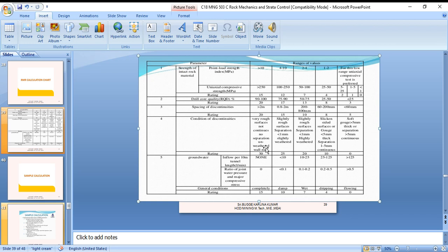Depth of the excavation, width of the excavation, and angle of fractures are also taken. Protodyakonov's coefficient is also one of the estimation factors. It is also assumed that an excavation pressure arch, a parabolic shape, is formed, and the weight of the strata lying outside the arch is transferred to the excavation. Different theories are also available for scientific analysis purposes.